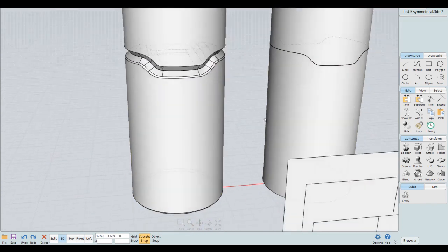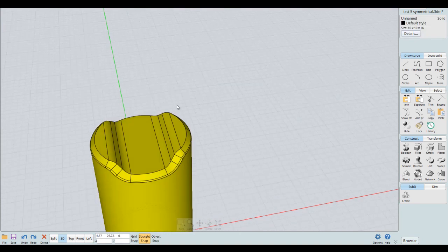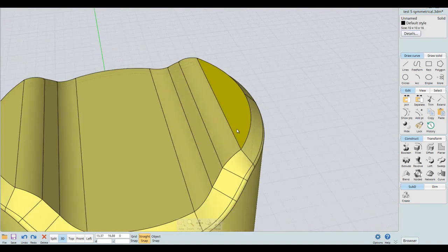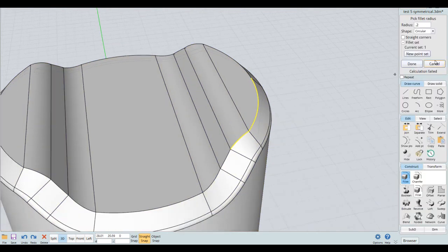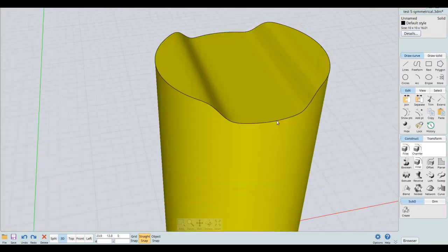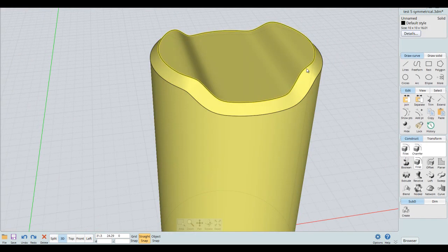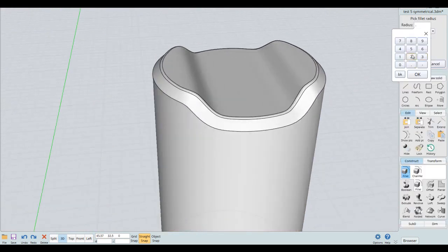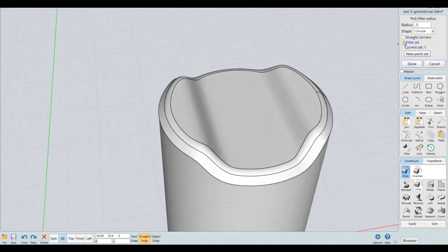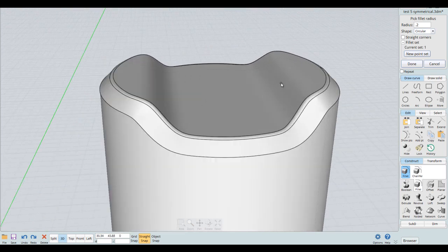But if you want to get more detailed with your designs here, these edges will eventually cause issues, as they're causing issues for us right now because I just can't fillet this here, even with a reasonable value like 0.2 or 0.1, for example. However, if I then chamfer this and then select this right here, let's fillet, and as you can see, 0.2, no problem. Even probably 0.5 will work just fine. So in this situation, now after the rebuild command, we have no problems here.